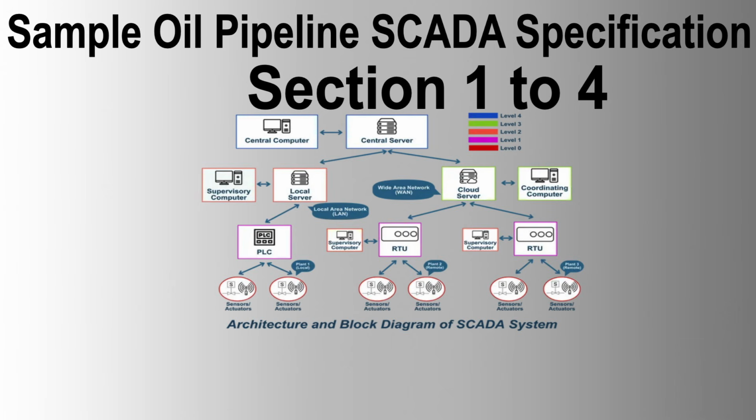4.3 Supervisory Control. The operator interface shall transmit control commands to the RTUs and verify the success of the control action. A defined time period for a field device to confirm the control action shall be set in the database. An in-transit state should be displayed to show the operator that control is in progress. Invalid control requests shall be rejected by the SCADA system master station. The system shall use a true select verify command control procedure to prevent undesired commands.